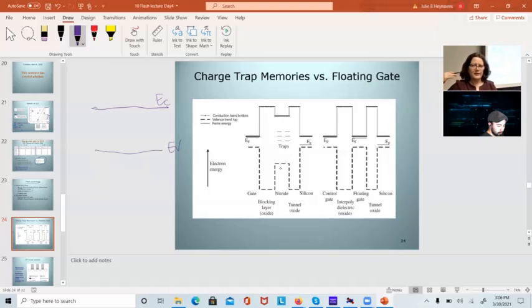Now, this may be ultra pure silicon with maybe only 1 part per billion of impurities or something like that in there. But there is that 1 part per billion. And this 1 part per billion happens to be an atom that has an allowed energy state somewhere in this band gap.